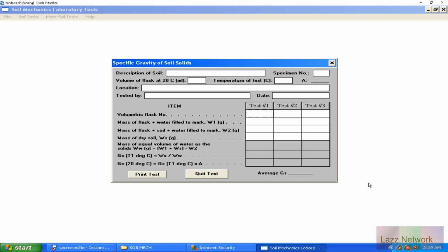But other than that, for processing it, you've got all kinds of different ways you can do it. For AASHTO, it says you're going to boil it for 10 minutes, but that's after you let it sit for 12 hours in the pycnometer with your deionized water covering the sample, but not filling your pycnometer up to your calibration mark.